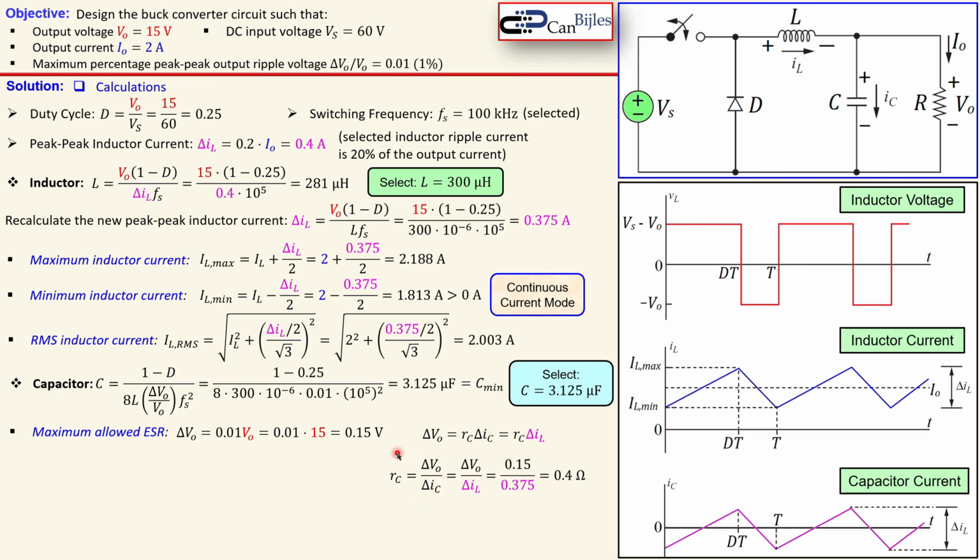And so if you select your capacitor, which is 3.1 microfarad, for example, you cannot manage this value. You need to maybe go up or go down and then maybe adjust other parameters in order to stay in that vicinity of your output peak voltage ripple.